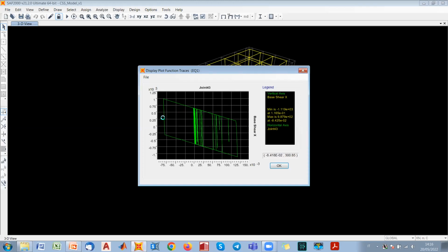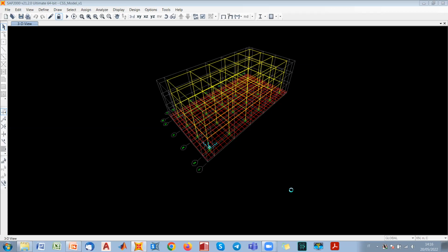So this means that we can also expect a certain agreement between these results and the results that we obtained yesterday for the single degree of freedom oscillators. Here we just consider the theoretical behavior, and here this is obtained also for the 3D model of the overall structure. This happens because for one location, which was this isolator, when the motion causes an increasing value of axial compression force, at the same time, at the opposite location, we have a decreasing value of compression. So on average, the response is equal to the theoretical one.